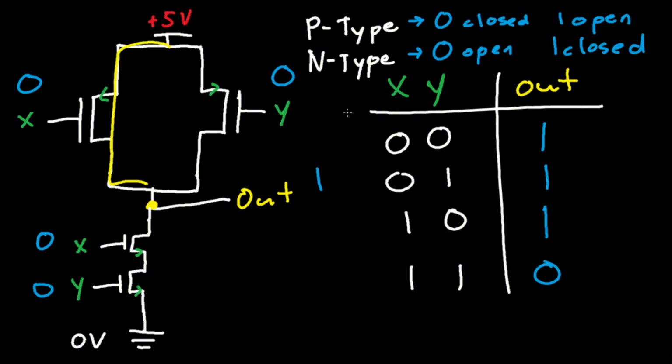Current goes down here, boom, hits this node, and current actually gets cut, because these switches act as open switches. When you have logic 0, these N-type gates act as open switches. Therefore, this current can't reach ground. If the current were to reach ground, again, your wire would melt, basically. It would heat up way too much.